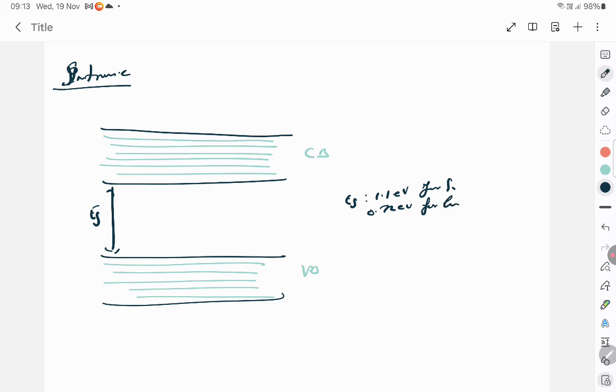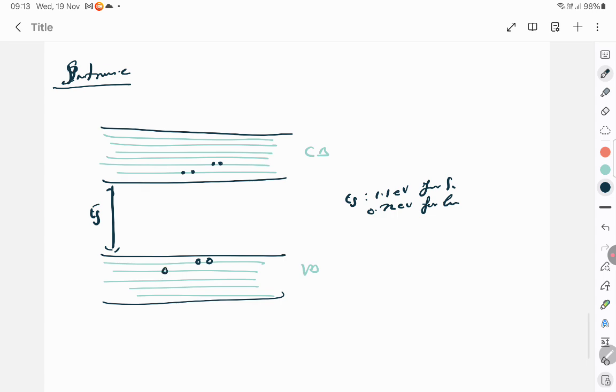When an electron jumps, in drawing, electrons exist as pairs in dumbbell shape. So the number of electrons here is 2 and the number of holes is 2, because you want to show that Ne is equal to NH. If you draw 2 more electrons in the conduction band, then draw 2 more holes in the valence band. Don't leave the valence band empty; you have to have more electrons in the valence band. What is in the conduction band is what is going to conduct.